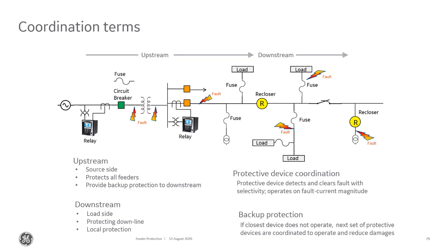The problem is, if the recloser does operate on the high speed curve and it closes back in, the recloser now switches to a slow curve. Now, if the feeder relay is still on the high speed curve, when that recloser closes back in on its slow curve, the relay is going to trip. Again, not the desirable situation.